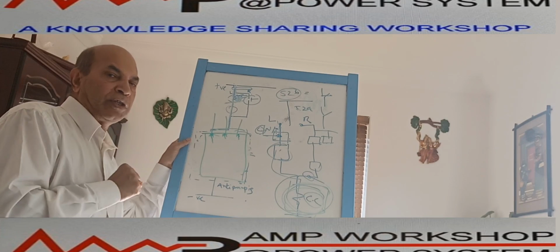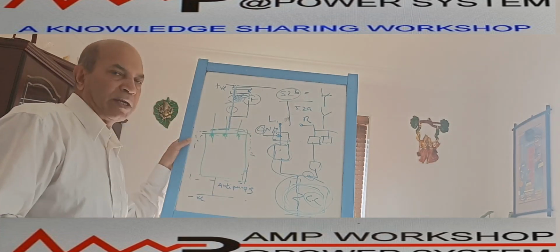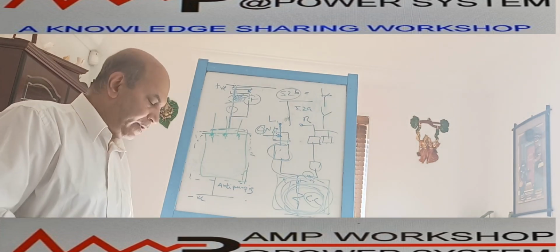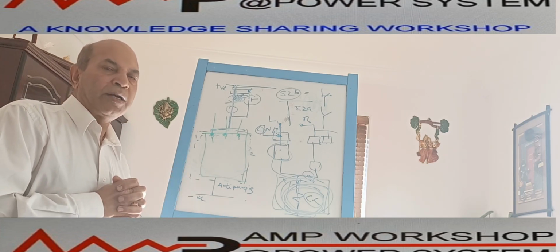It is a part of the closing circuit. These details we have not discussed in the last video, but if somebody is interested to know about this, this is the brief explanation. This part will be inserted in the closing circuit. This entire thing is coming inside over here. It is inside a breaker chamber, and all of it is connected through the pin configuration. Okay, this is called the anti-pumping circuit or anti-pumping relay. So this is about the closing command issue which was commented on. This is the brief auxiliary video we made to understand the anti-pumping relay.